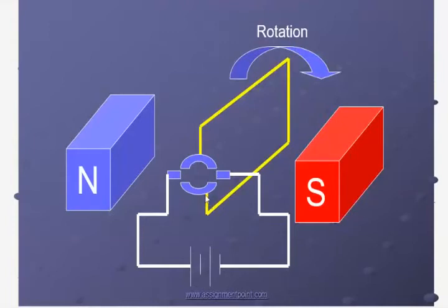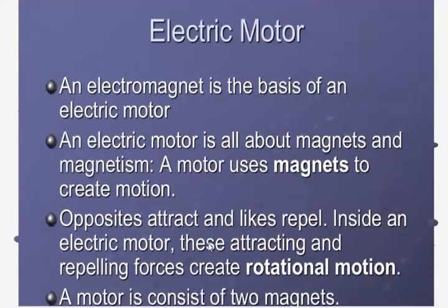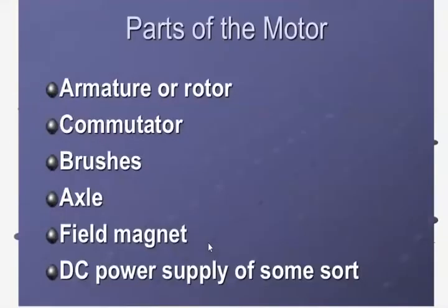Only you have to replace this ring, and in place of it, you take two complete rings, not a split ring, and arrange them. Connect one complete ring with one terminal and the other complete ring with the other terminal of the coil. Then this becomes an AC motor. The only difference is changing the commutating ring; the electric motor is converted from DC to AC.